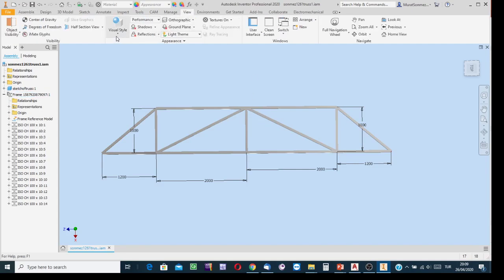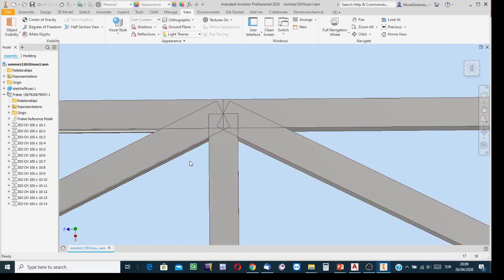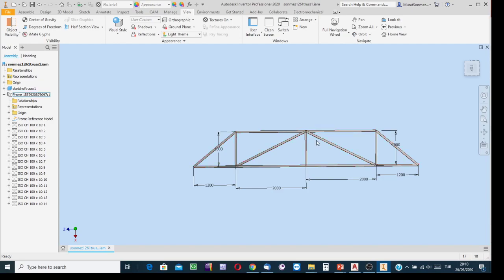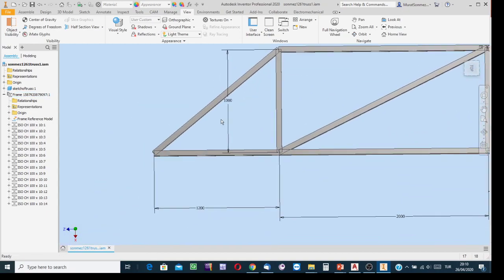Okay. After making such a highlight, focus your attention on some problems. Yes, Inventor created the model of the structure in a few minutes, but when we zoom in at the joint, we can see that there are unrealistic things. This member interfered with the other member. In the physical world, it is impossible. How can we have within a solid body another solid body? There is an interference here between this and that, between this and this, and the others. It is a problem and it is to be solved. And at this joint, again, we have unrealistic interferences.